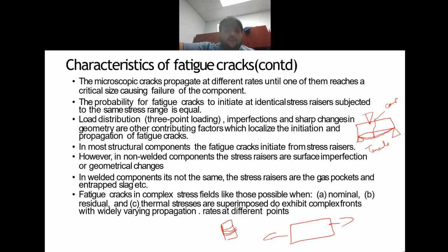So let's say, let me close this video. Let's say I have a welded component. Then in a welded component, that doesn't matter much. Okay, there are two reasons why a welded component would fail in fatigue. One, basically, the weld point is going to create a surface roughness in the material, and that surface roughness becomes the reason why a surface crack is initiated from that point.